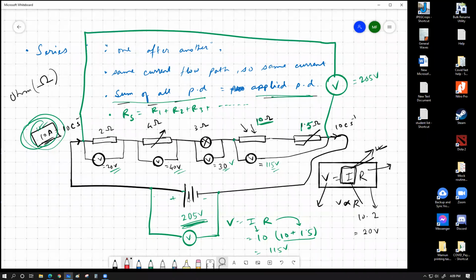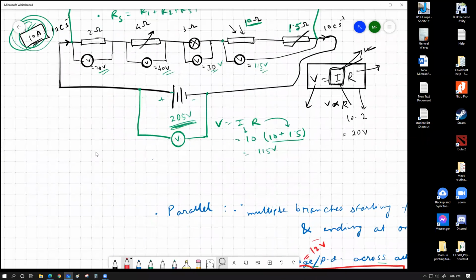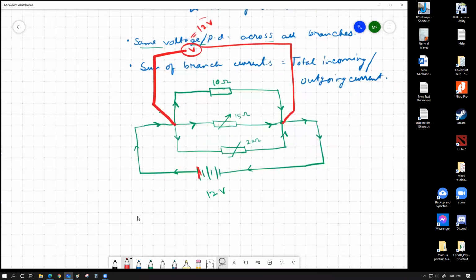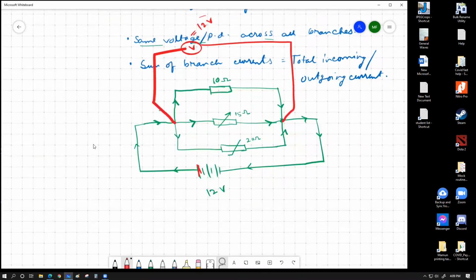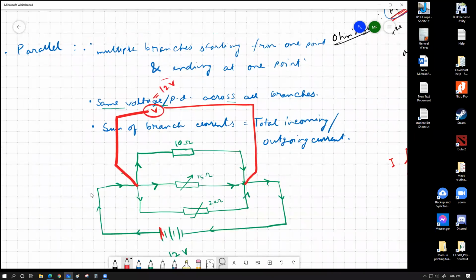this battery. And electrically, this green point and this green point are electrically equivalent, and this point and this point are electrically equivalent, because there are no voltage dropping agents, or no electrical components, across these points, so they have the same voltage value. This is the same principle that we applied over here, only I did not draw another voltmeter at that lower side, but the principle is very much the same. So in this case, the voltmeter would read 12 volt.